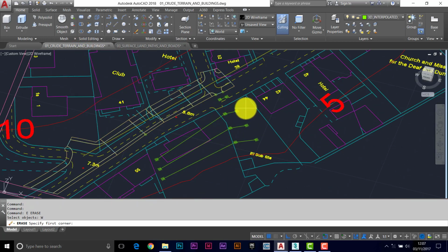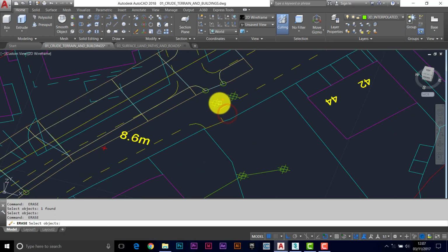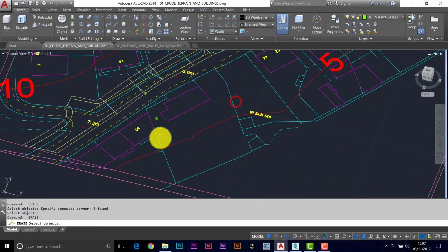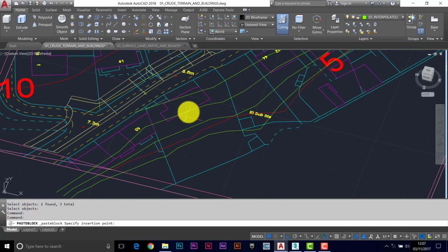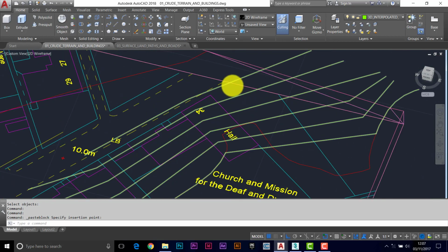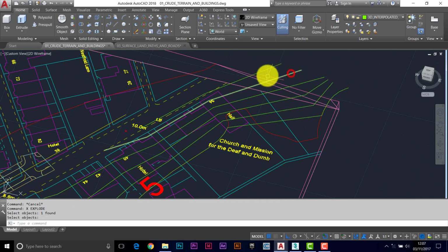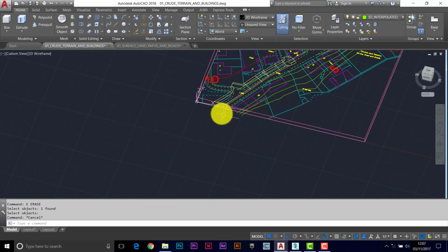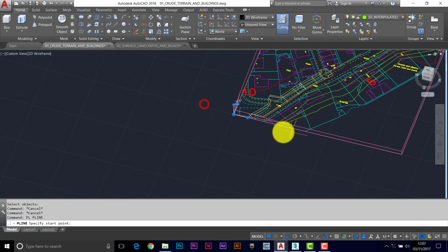So we'll clear these away just now because we're bringing in a batch of new ones. V, put those there. Okay, I'm going to trim off the ends of these ones. I'll explode it. Trim off the ends of these. And similarly down here.